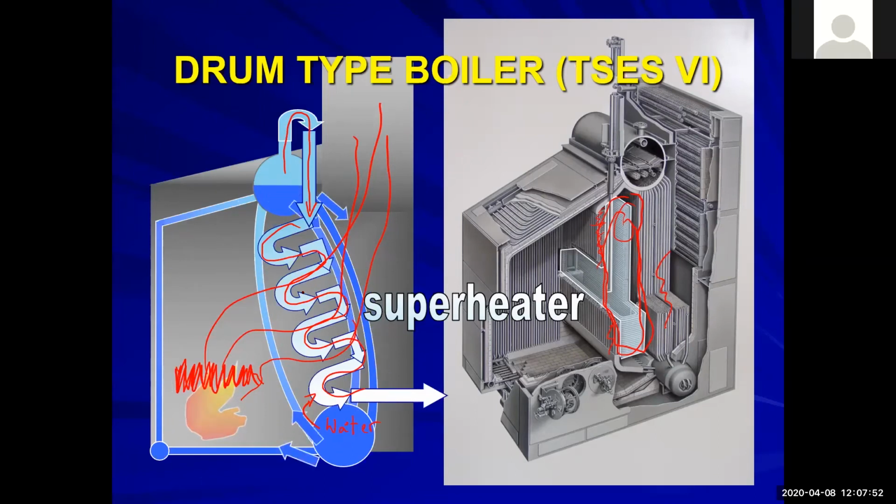Wasn't it because the heat's going to pass over that area, going up to the stack, right? Exactly. It's going to pass through it anyway. But what's inside of our superheater and what's inside of our generating tubes? Water's in the generating tubes and steam's in the superheating tubes. Exactly. So what do we want to do? What do you think our main goal would be for why we would want to have our superheater between generating tubes? Then have them on a direct source of our heat.